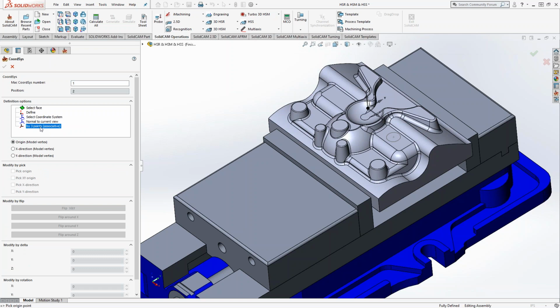By 3 points associative is literally if I only have points to choose from. It could be from either a print, like a DWG file or a DXF file that I've translated into SOLIDWORKS geometry, or it could be a solid that has no sharp edges, no flat faces, no straight lines. It's all just pure vertices. Or maybe you've translated an STL file, something like that. With the by 3 points associative, you start by choosing a vertex or a point that represents the origin.